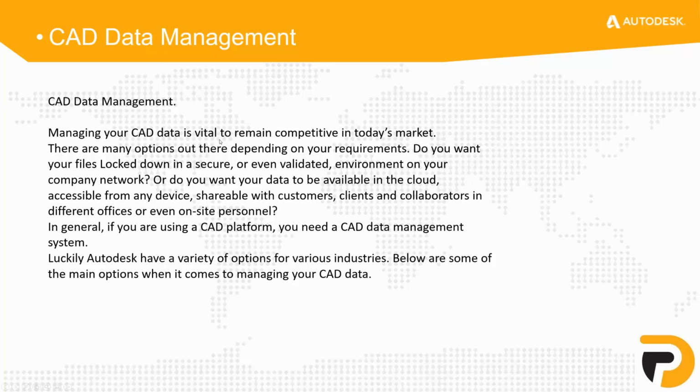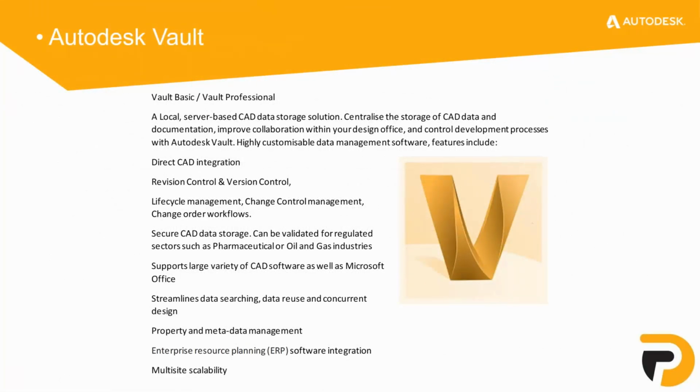So Autodesk have a variety of options, and I'm going to go through some of them here. Vault, I'm guessing a lot of you might already be familiar with, since this is a Vault webinar that explains one of the functionalities of Vault. But just to briefly go through it, Vault is a local server-based CAD data storage solution. Basically, you have a server on your site, and the Vault server application is installed on that, and each CAD user in your office has the Vault client application, and that allows them to check files in and out of the Vault. It includes stuff like revision control, version control, lifecycle management, change control, change orders, ECOs,